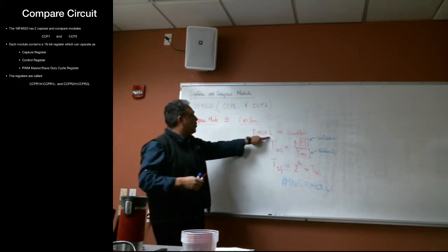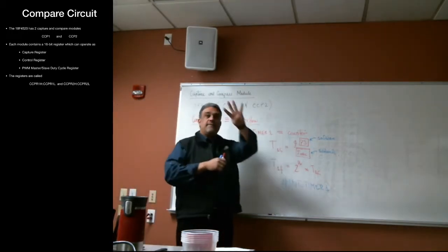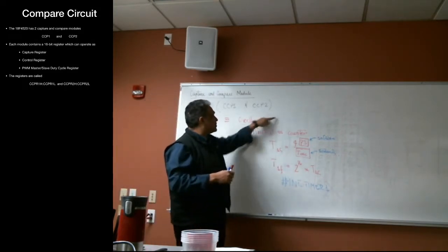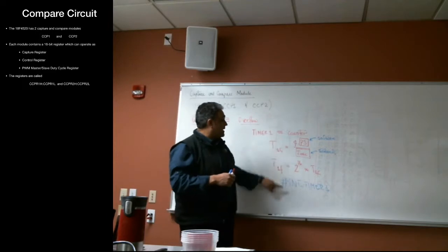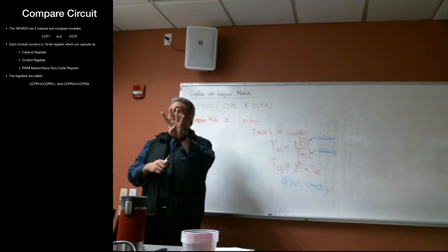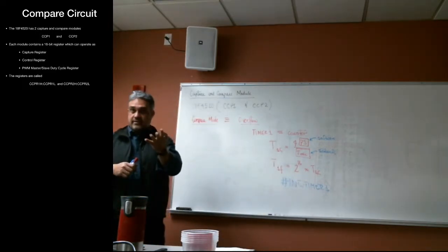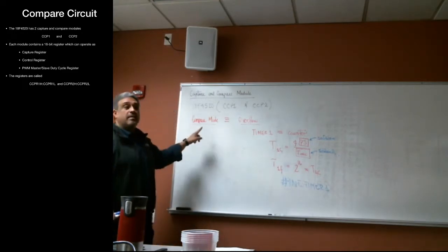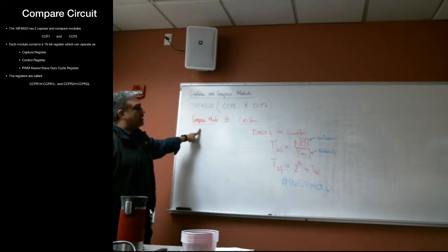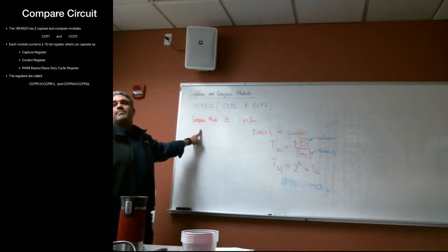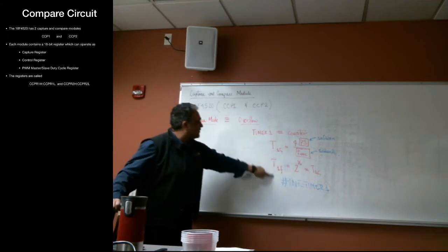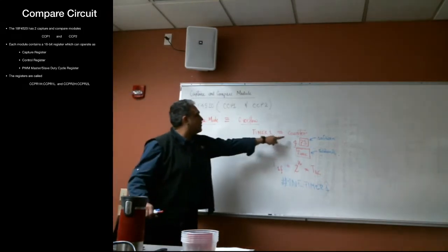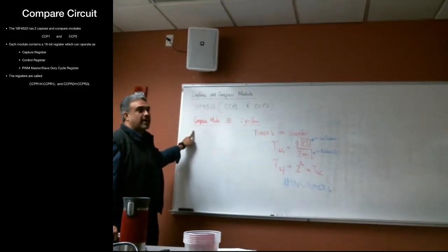Now, on timer 1, we knew that there is only 4 prescale values, which means that if I'm going to use an overflow circuit on timer 1, I can only generate 4 different frequencies, right? All right, so why is compare mode so useful? Compare mode will actually give me really high precision on the amounts of frequencies that I can generate, all right? But instead of using my overflow, I'm going to start using a compare system.